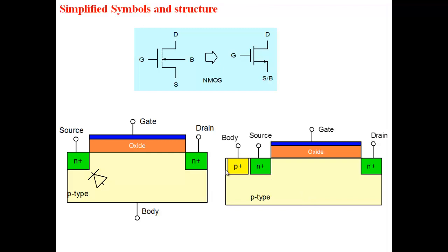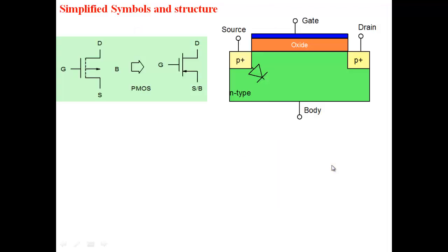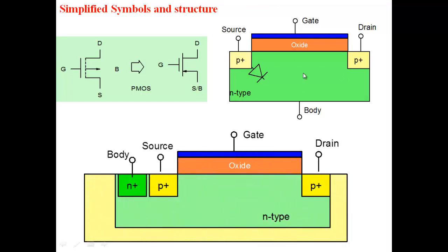So note that MOSFET is a planar device. All the contacts are at the top. The source, body, drain, gate, everything is at the top. Okay. This is for the P type. Similar gate, drain, source. The arrow is pointing out, and the arrow here points in gate, drain, and source here. So this is the P type semiconductor, P type MOSFET here.